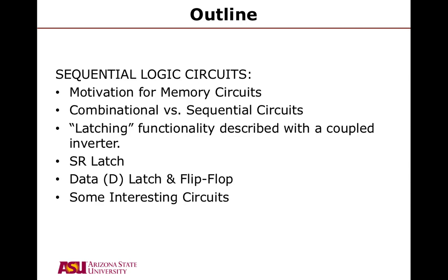But I'll touch upon memory circuits, and we'll go over the difference between combinational versus sequential circuits, where combinational is what you have seen to date. And then I want to describe the latching functionality for you in the simplest form, which is using a coupled inverter. And then we'll go into an SR latch and then a D latch, which is derived from an SR latch. So you can see the SR latch, the last schematic that we will look at is actually the latest form of the SR latch, which is memory.